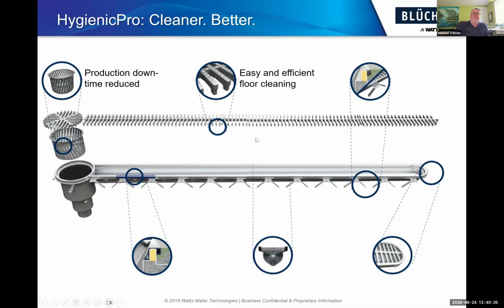So next is easy and efficient floor cleaning. We designed a grate that is cast stainless steel. Because it's cast, we don't need to build a frame to weld bars across it. We can have a spine and just have fingers reaching out to the edges. So as solids are coming across the floor with water, there's nothing preventing them from getting down into the channel. A few slides back, we saw that brewery where the epoxy floor was starting to flake off.